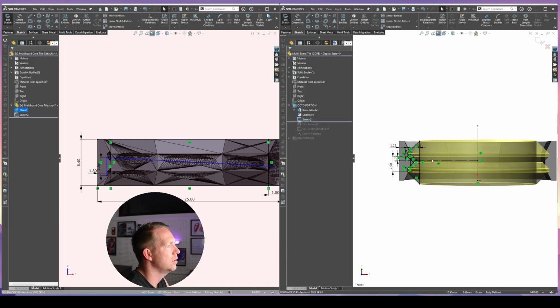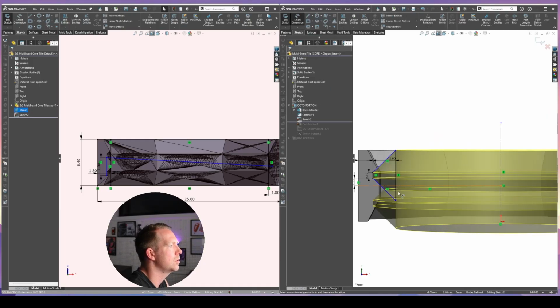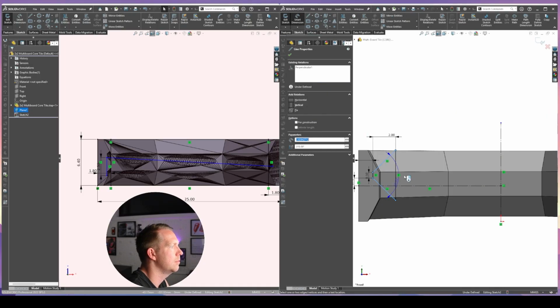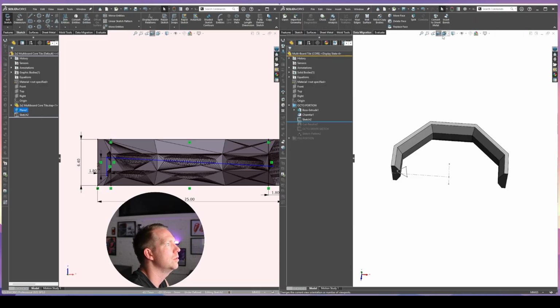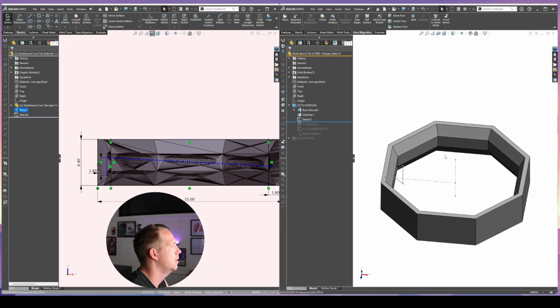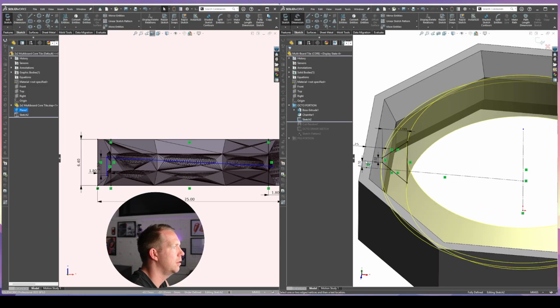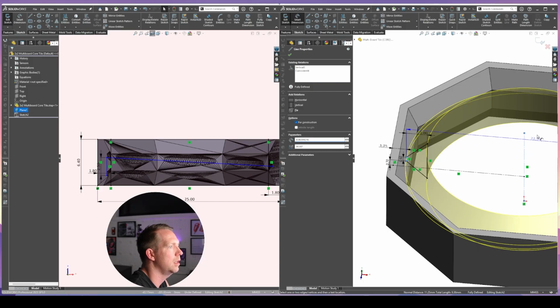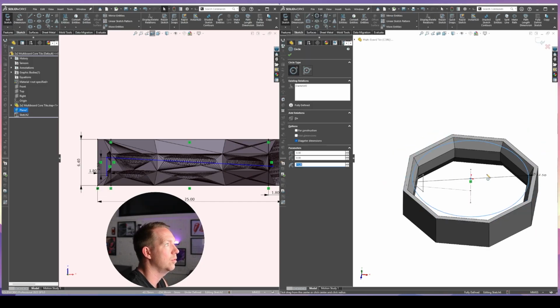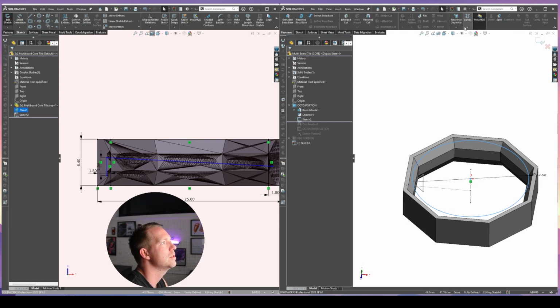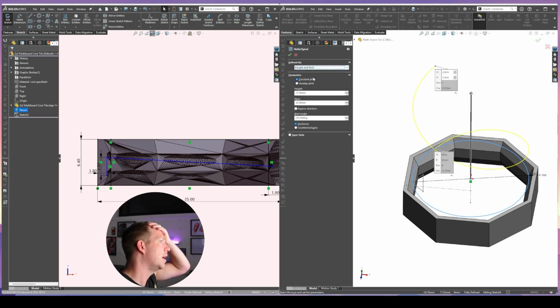So I think we can just use that. I think what we're going to do is change this sketch. What dimensions does it need? We're going to add some, no, they're already 90 degrees. They want to be equal. What we want to do is our spiral, and our spiral is going from this to there, 22.5. So here's how we're going to do it. Circle, 22.5. We're going to go features, curve, helix, height and pitch.